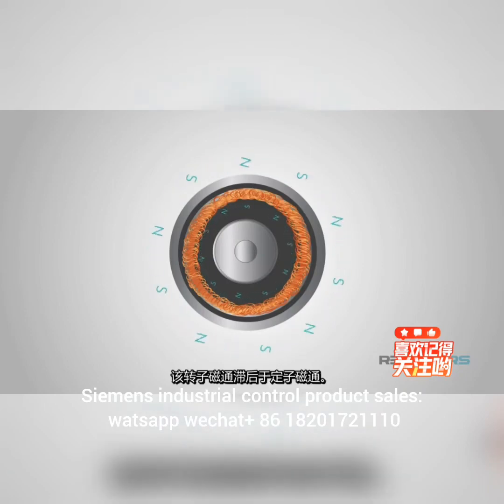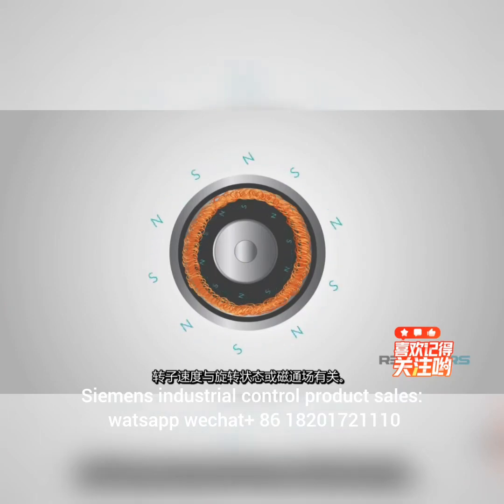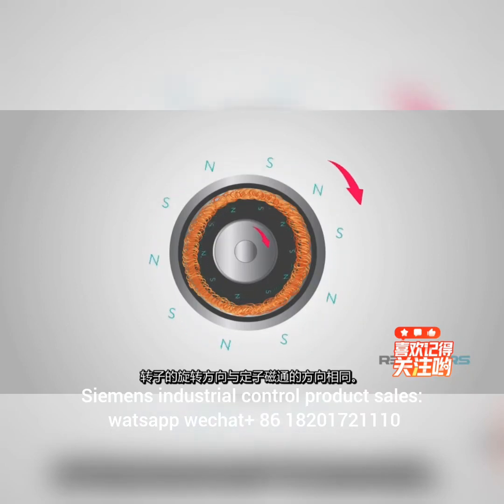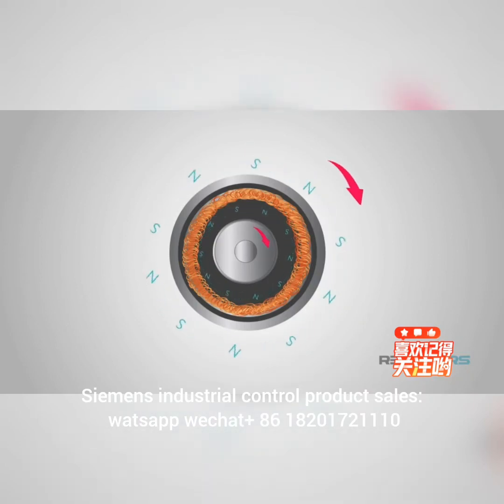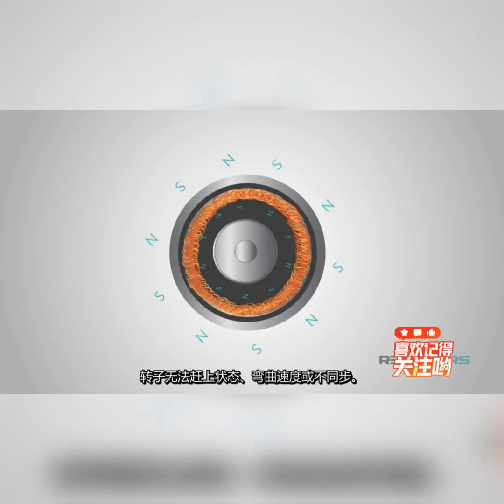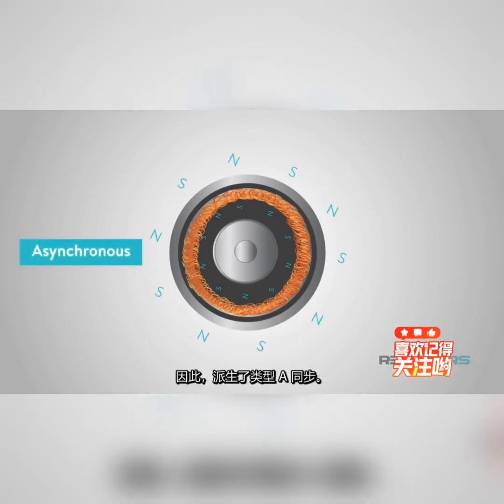This rotor flux lags behind the stator flux. The rotor velocity is related to the rotating stator flux field, and the rotor rotates in the same direction as that of the stator flux. The rotor does not succeed in catching up to the stator flux speed, or is not synchronized, hence where the type asynchronous is derived.